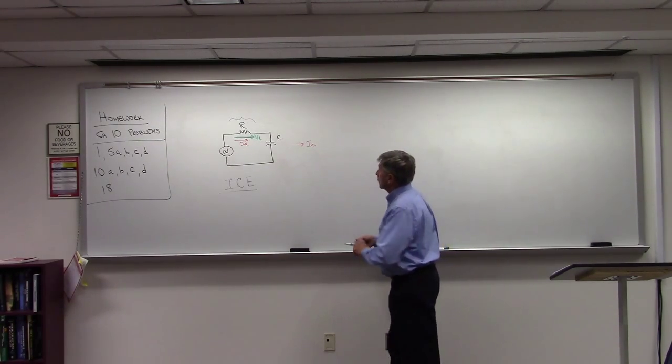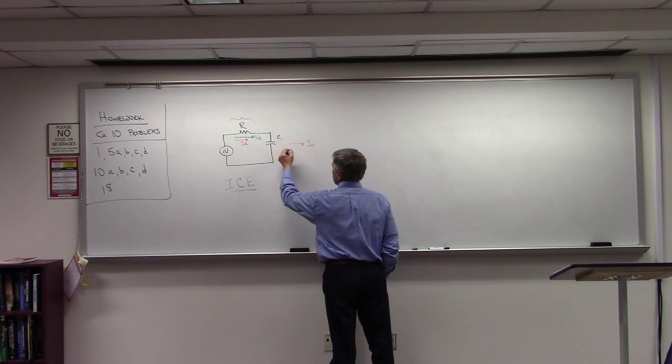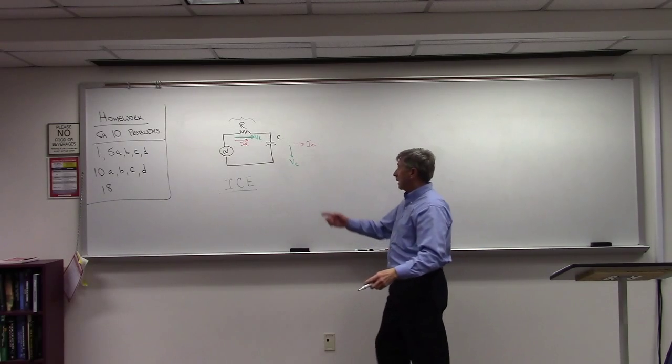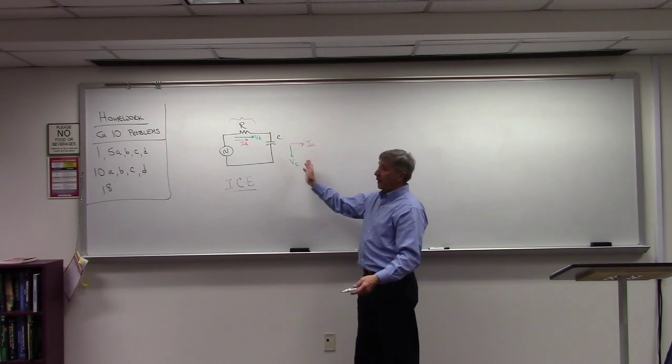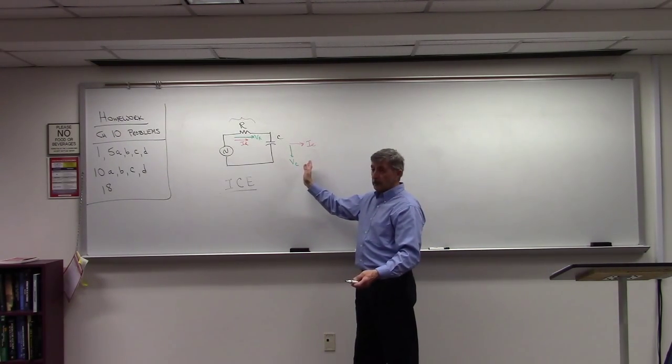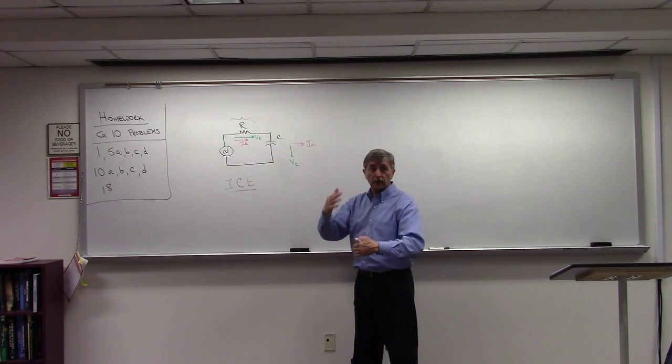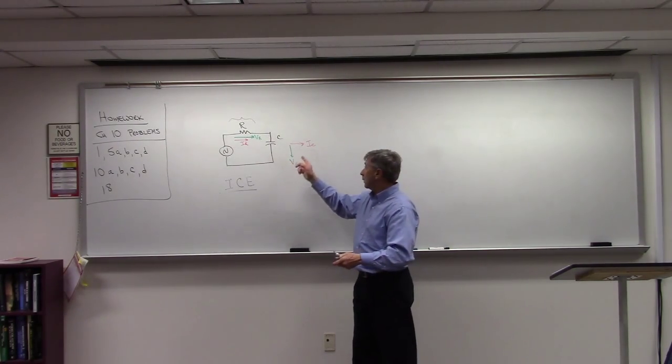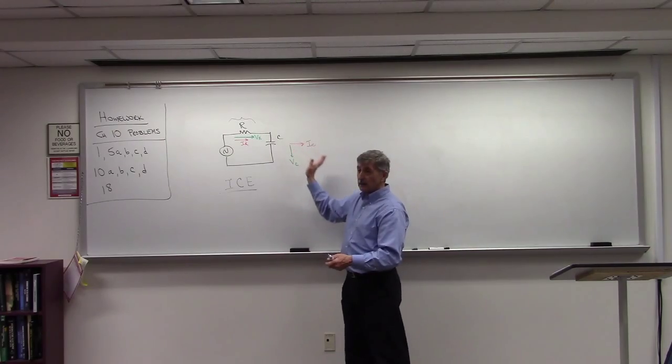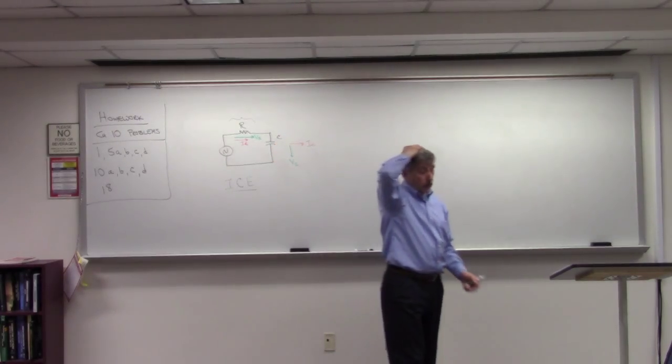So the voltage across that capacitor is going to lag the current by 90 degrees. I drew it down this way because our reference direction for the rotating vector, the phasor, is always counterclockwise. So this guy, IC, is always leading the voltage if you're going counterclockwise.